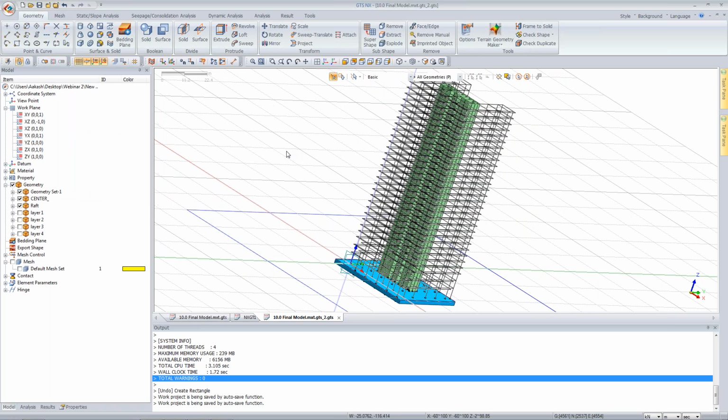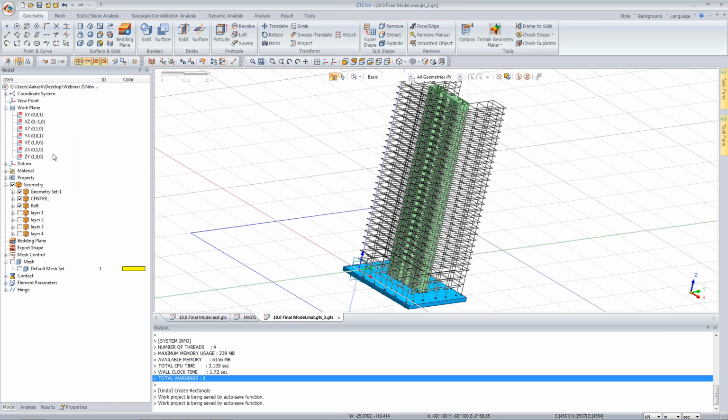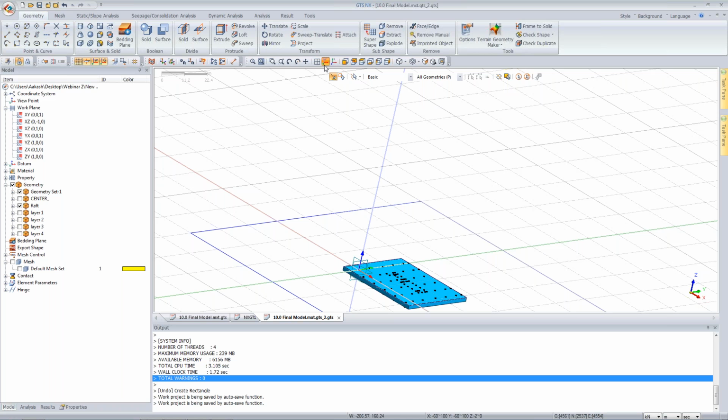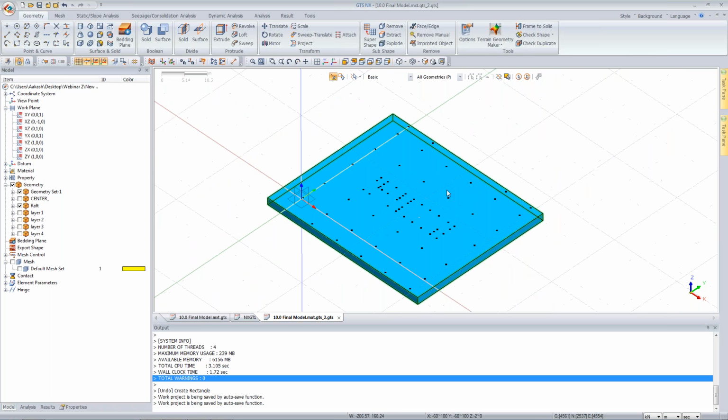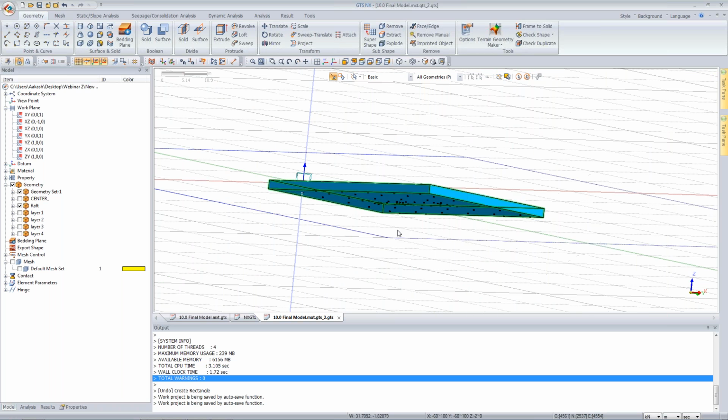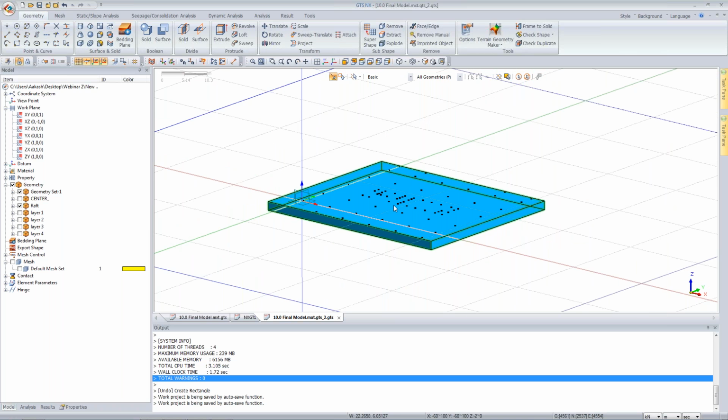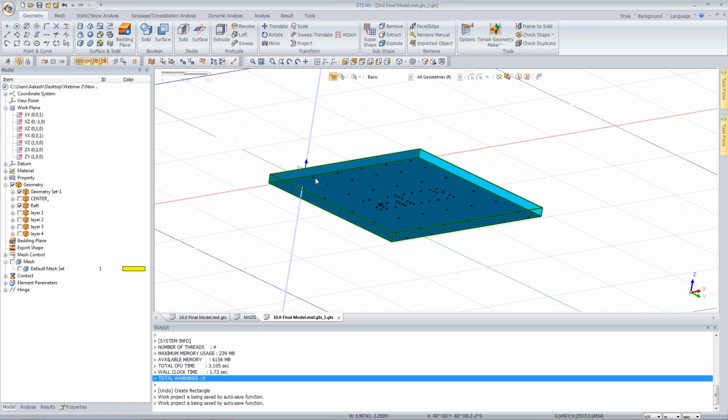So what happens now as a result of Imprint, if I can hide this building for you? Now you can see that there are points created at each of the column locations, at the top and the bottom. The top is a must. The bottom I'm using for this model so that I will extrude this point to create my piles. Clear?